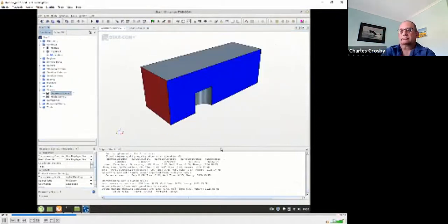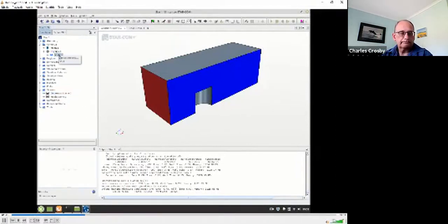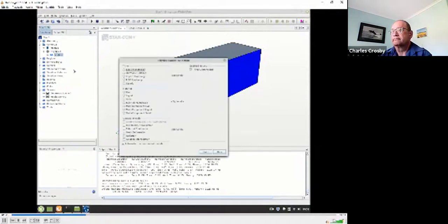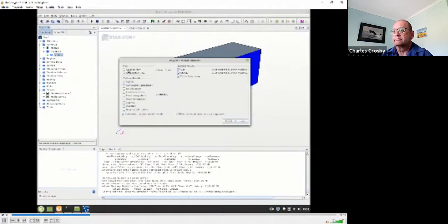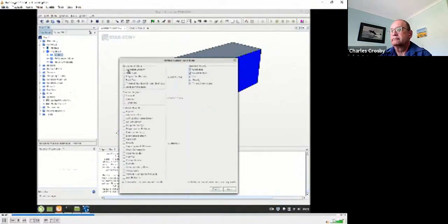Having now finished generating an acceptable mesh, we've got to set up the physics of the run. So we've got Continua and a Physics tab here, and under it models that we can select. So we select models from it here. We're going to do as before. We're going to use a steady state simulation. We're going to work with a gas only. We'll use, in this case, a coupled flow solver.